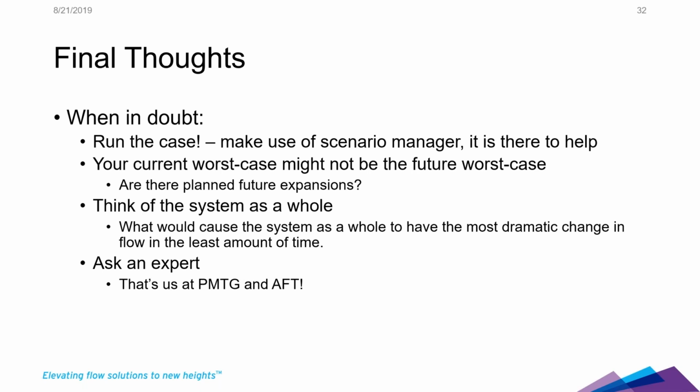Maybe you can't buy the equipment now because that's future mitigation. But maybe you can plan on adding a T at some point with a flange on it, where you can say, okay, this is where we're going to connect future surge mitigation equipment if we need it, at minimal capital cost right now.